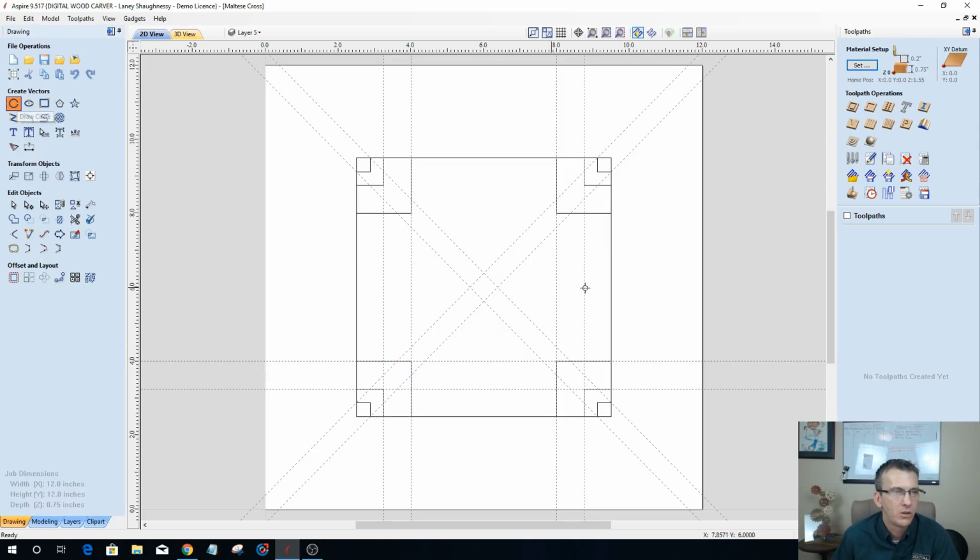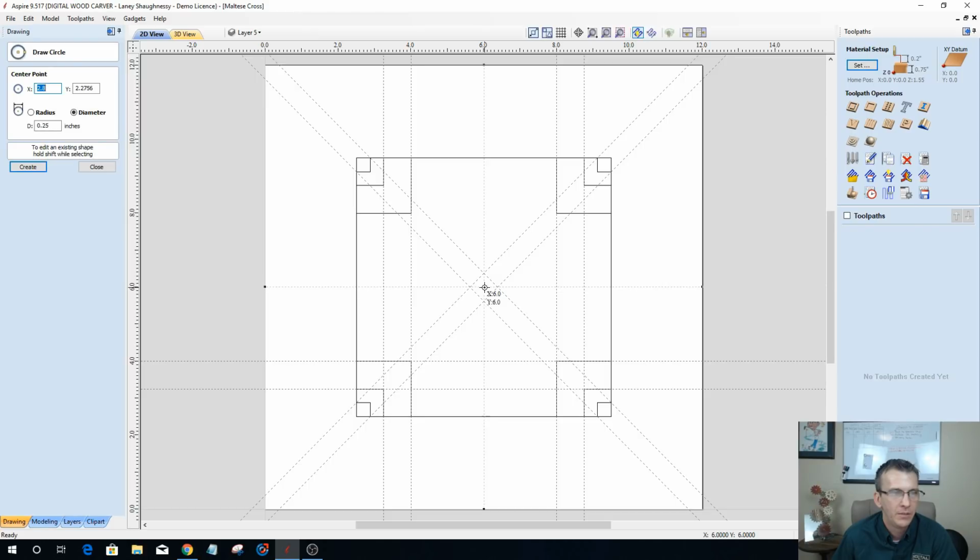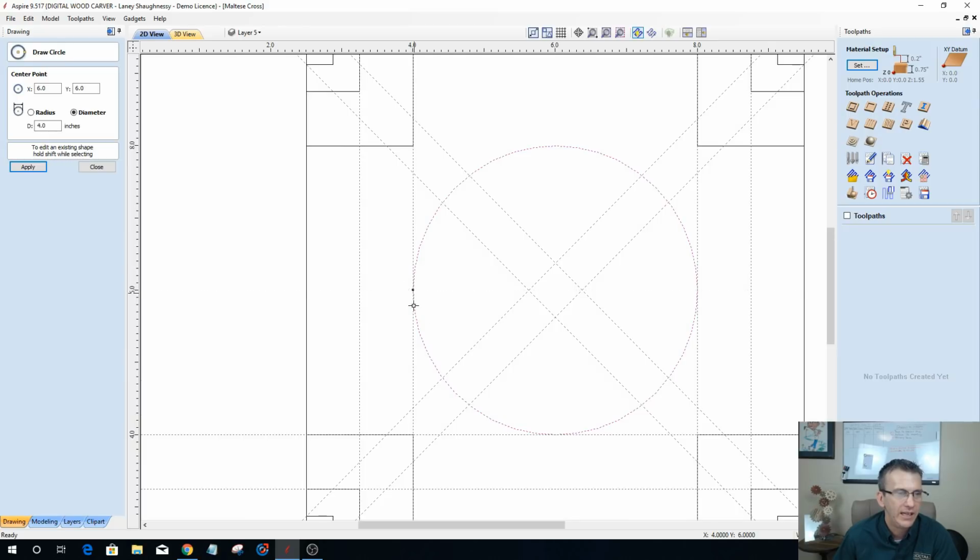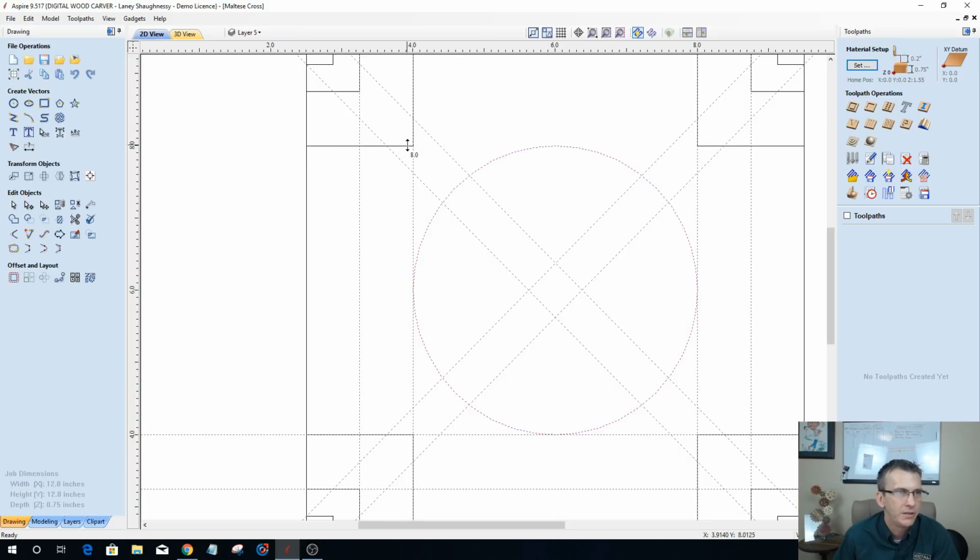So if I open up my circle tool, I'm going to start from the middle of my board, drag a circle out, and snap to that guideline, which should snap to this guideline on the edge and this one on the right. Now I don't have it. Let's put a guide up here just to be consistent. Let's close this tool and throw a guide up here so you can see. So the center circle here should align with all 4 guidelines of that inner rectangle that is made by the guides, but that is determined by that 1.5 inch square on the 4 corners.